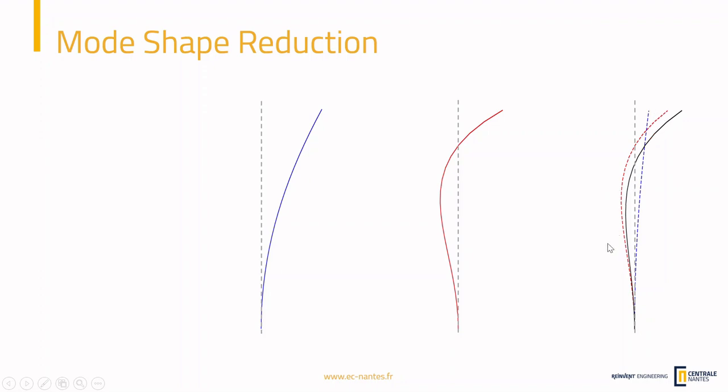So what we need to do is just know the modes of the tower beforehand, and then we need to know how much of each mode composes the final motion, and we get the motion of the tower with just 2 degrees of freedom, which are the displacements in the first two modes. So we gain a lot of computational time by using this method, and this is what ElastoDyn uses. The only drawback is that you need to pre-compute the modes before running the simulation.